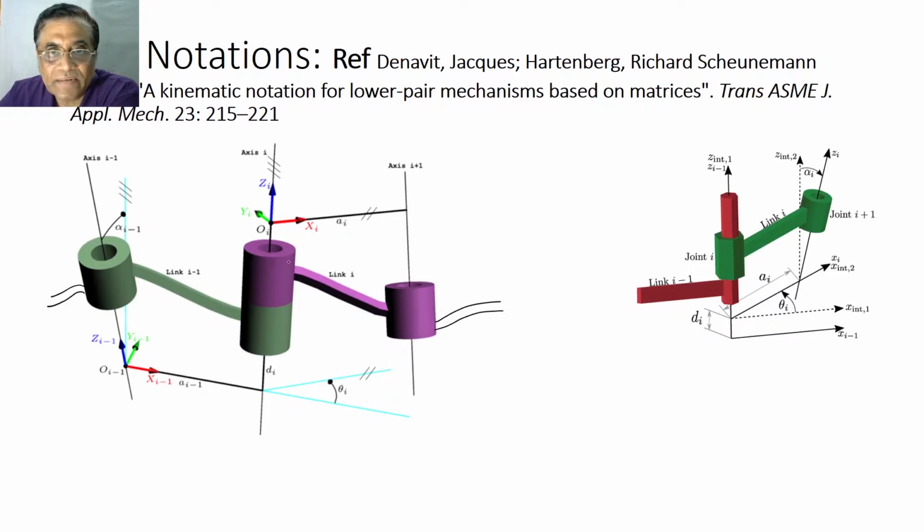There are 3 joints, and the Z axis will be assigned here. So this is Z i plus 1, this is Z i, and this is Z i minus 1. You see this link, as I told you, has a twist, and the twist is in this purple color link i. It is twisted in a clockwise direction; this end is twisted with respect to this end.